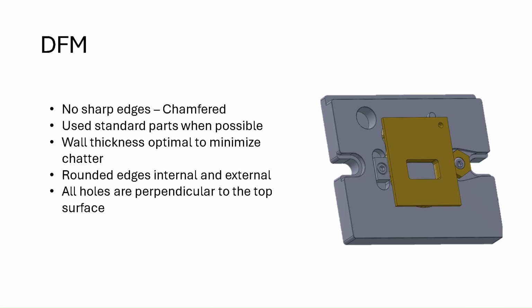For the DFM, we made sure that there were no sharp edges. We used standard parts when possible. The wall thickness was optimal to minimize chatter. We made sure that there were rounded edges internal and external, and all the holes are perpendicular to the top surface.